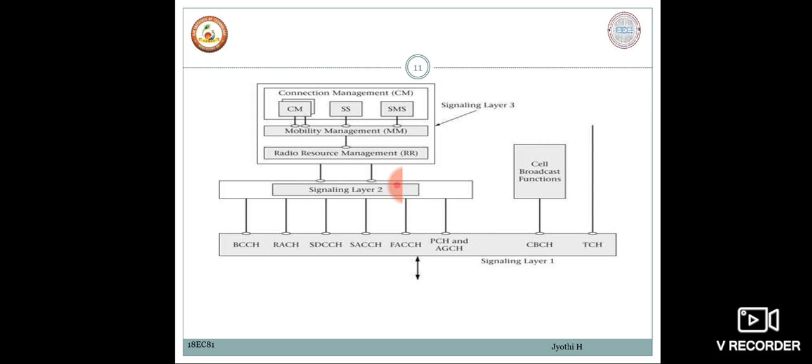To achieve this, the RR procedures include cell selection at power on, handover, and cell reselection during the idle mode. To recover from the lack of services during the idle mode, the cell selection procedures are performed in conjunction with layer 1. In fulfillment of GSM phase 2 recommendations for PLMN selection, the MS RR functions include the procedure for the reception of BCCH, that is the broadcast control channel, and the common control channels.